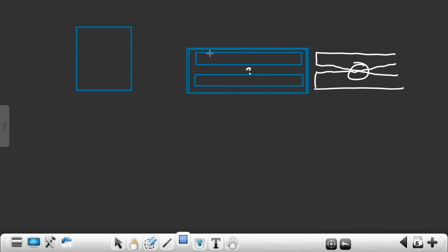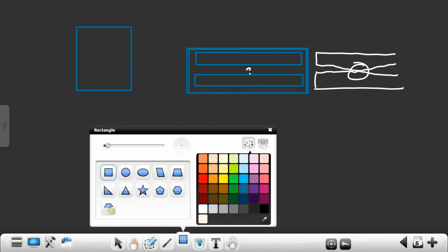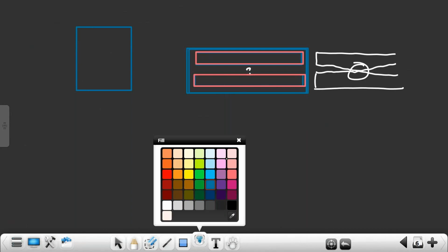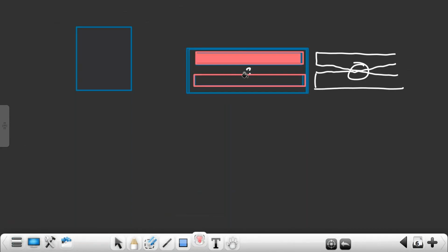And wherever they want to keep the metal layer, right, they will cover it through a mask. In this layer, what do I have to form? Metal layer. I'll cover it through a mask and oxide layer. They'll cover it through a mask and what? Oxide layer. And the remaining regions they will treat with highly concentrated acid. See, metal layers will react with acid and they will melt away. So all other regions will start melting.